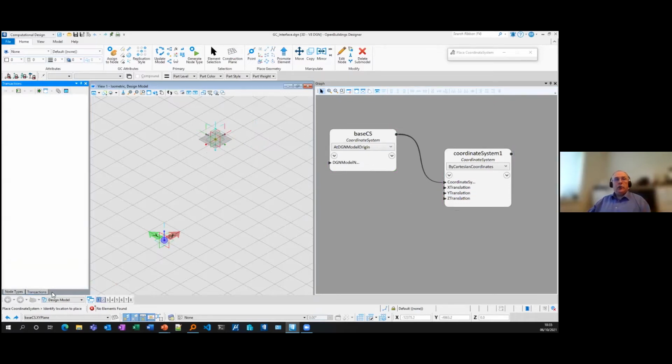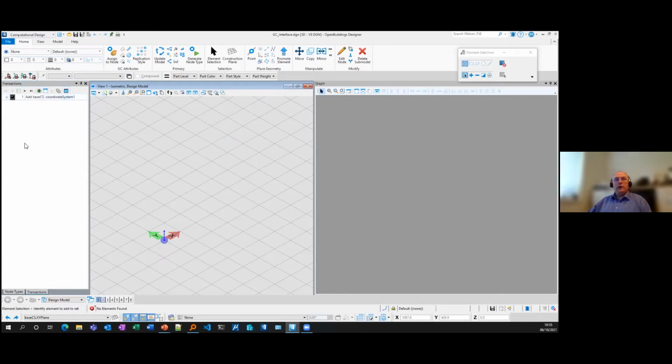I can then choose to record those steps using my transaction list. Now, there is an option to automatically record these, and it will give you every step that you've done. Here I've done 2 steps, but I also control it manually by clicking here at the top. And what that does is it creates an entry here in my transaction list. The transaction list is my history of what I've done, and I can actually unwind and rewind everything through that transaction list.